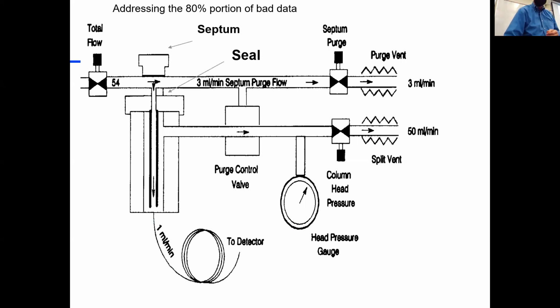Replace it routinely. There's a seal up here. This is glass, and that glass attaches to an aluminum block. How do you attach a glass piece to an aluminum block and not have it leak? Okay, there's a nice little seal in here, the septum seal. Again, a polymer. If that isn't changed, your gas flow comes down here and goes out around this direction. So again, you check the seal there. You check the seal up in this part of the instrument.